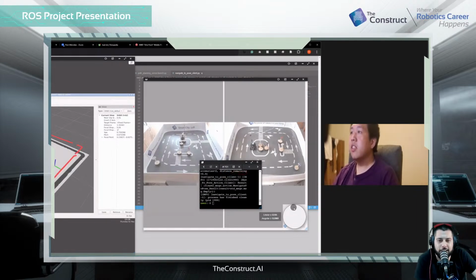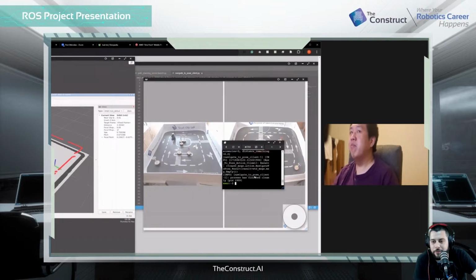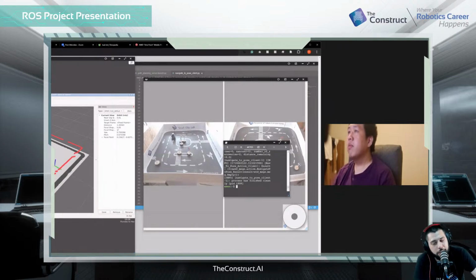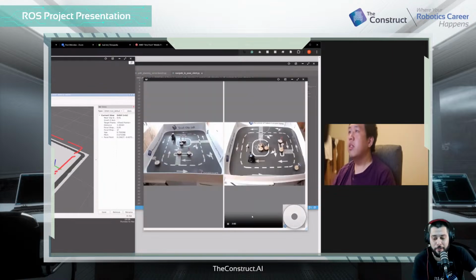Great. All right. Awesome. So did you send another one? Oh, you're moving it out of the way. I'm moving it out of the way. Okay. I did realize this, in the simulation at least: if your robot is too close to the obstacle, the LiDAR cannot see it, and that's bad. Yes, it will show up as infinite, but if you're running nav2 on top, it would not even consider it. What you would consider, though, is that you're on top of an inflation layer, so it would kick in a recovery behavior right away. That's what would happen.